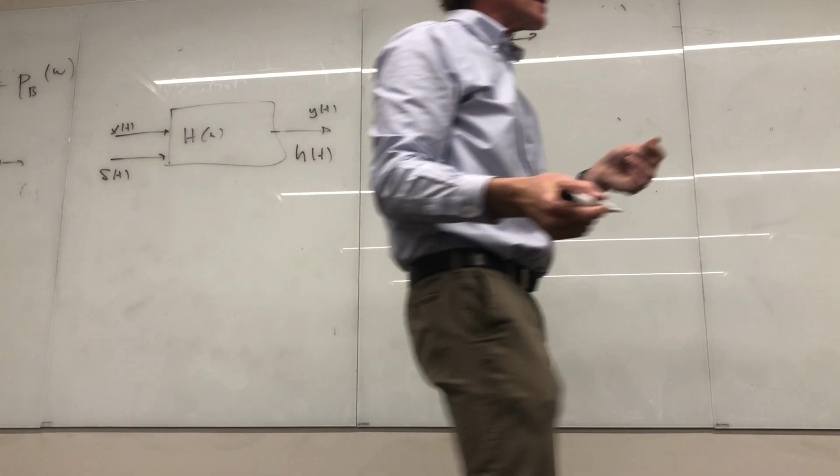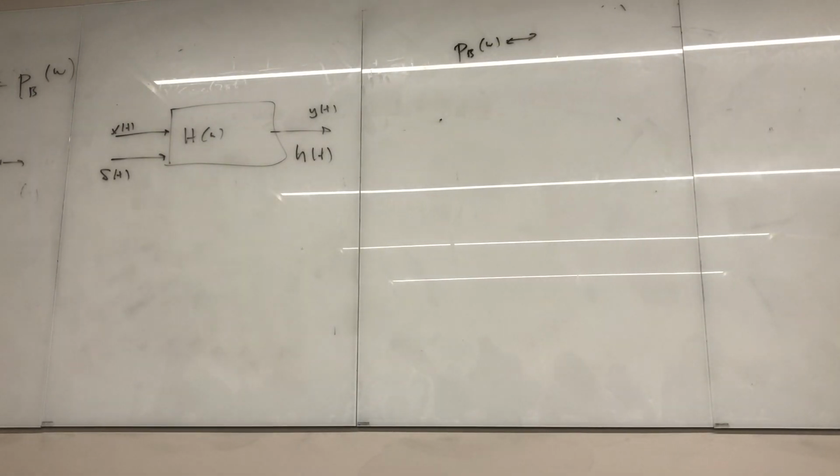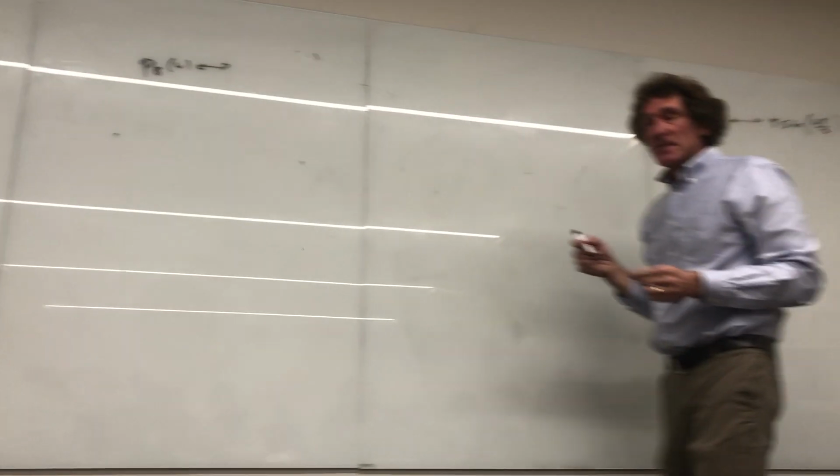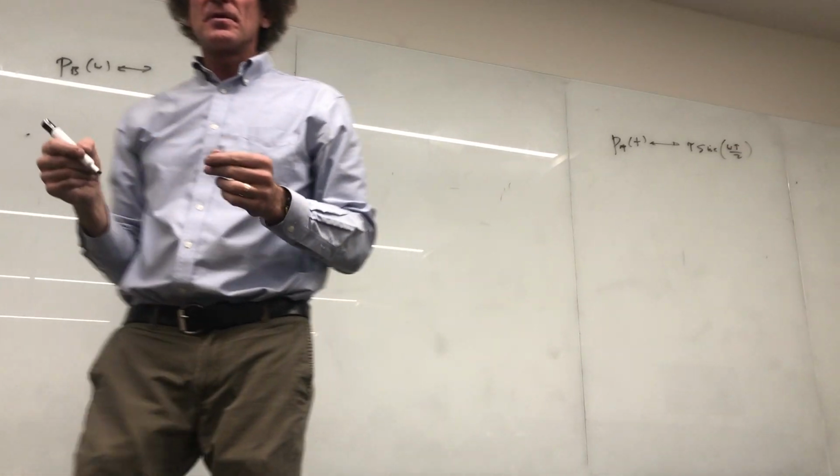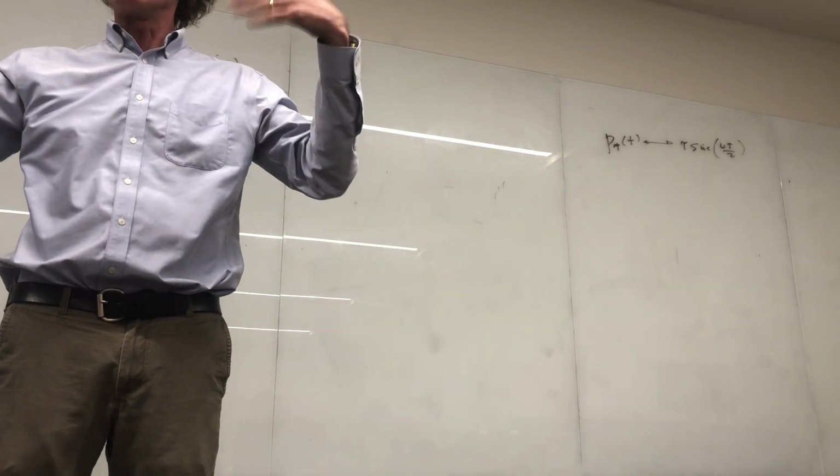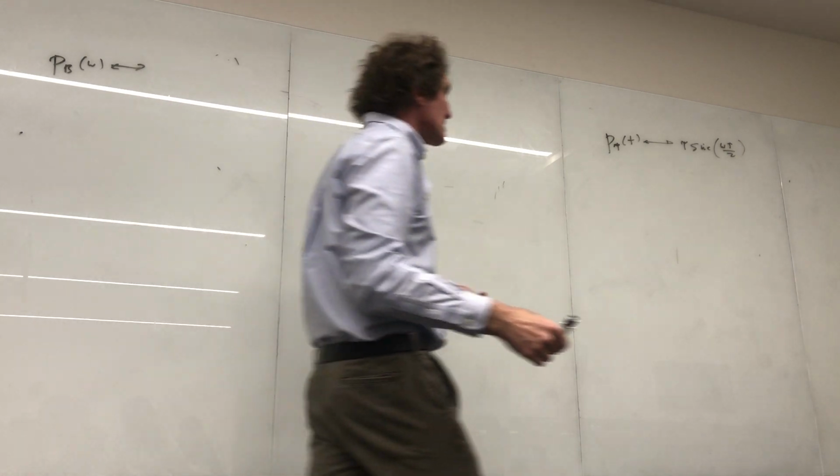So here we use duality, and I'm big on duality. I know that a pulse function of width tau, we just did this, by the way, goes to tau times a sinc of omega tau over 2. These you must know. You with me? I'm going to go through it slow here. Everybody got that? That has been done probably 20 times, 30 times in this class.